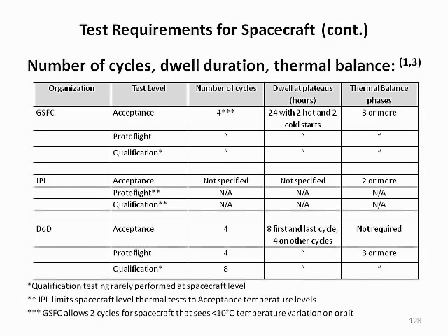JPL conducts all spacecraft-level tests at acceptance temperature levels. As noted earlier, qualification testing at the spacecraft level is rarely performed these days due to the high cost of building a non-flight spacecraft.